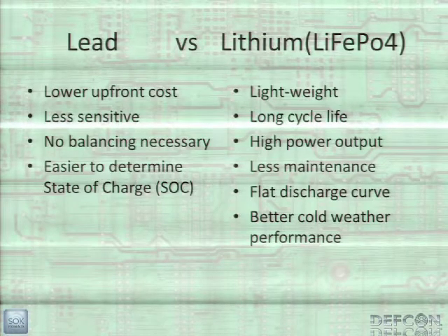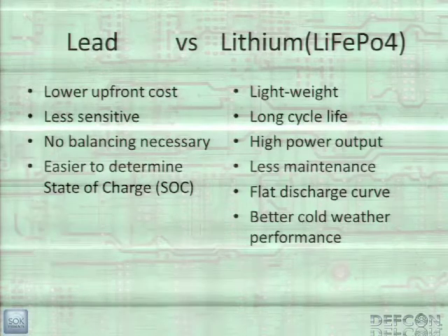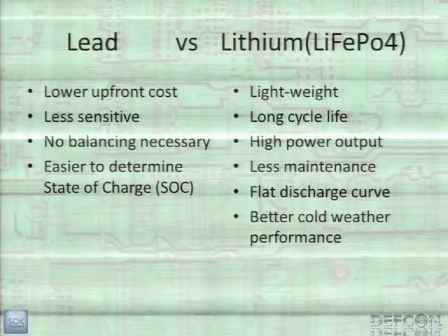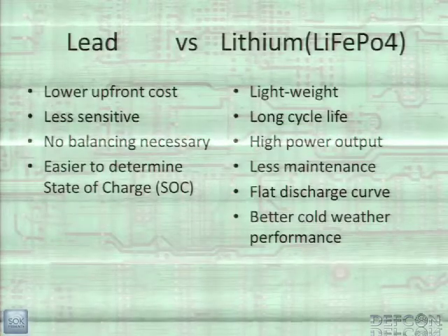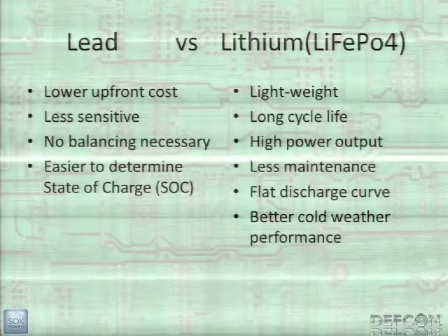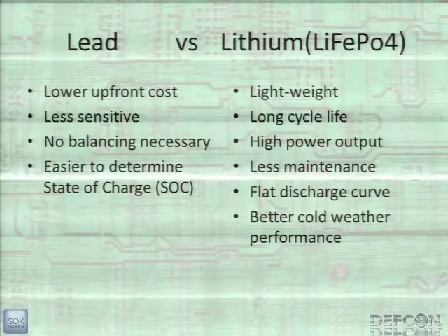Lead acid batteries, because they gas at the end of the charging cycle, you have to put water in them every few months to not kill them. Also, cold weather performance, lithium's a lot better at this. Lead battery will lose half its capacity when it's too cold out, and lithium will only lose about 10 or 15%. And if you heat them properly, then it's not really an issue.